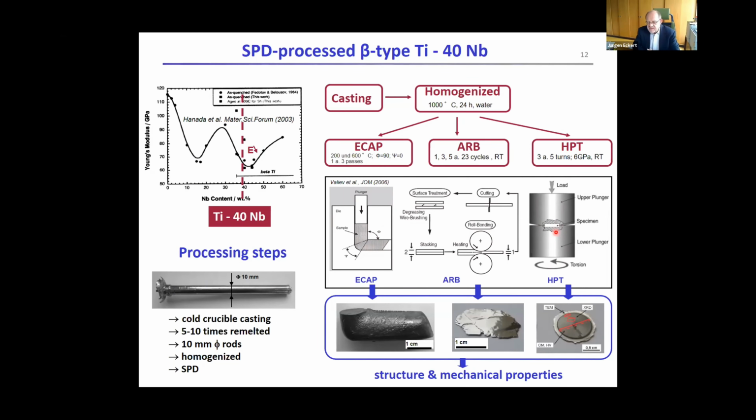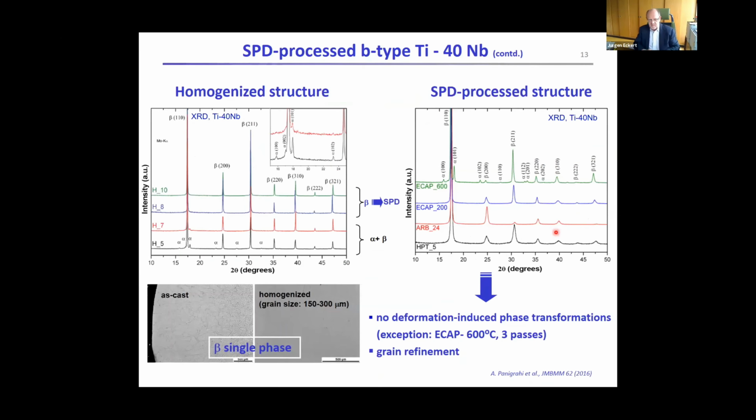Or you do a successive rolling procedure like we've shown in the middle part, abbreviated by this phrase ARB, which means accumulative roll bonding. So there are different mechanical deformation methods. The reason to apply these is because these methods allow you to gain an even more refined microstructure.